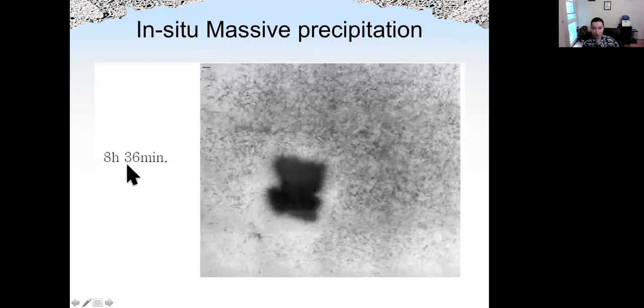This is 8 hours. We can see more hydration product precipitate on this cement grain, and also we have more hydration product generated in the water solution. When that happens, the cement is no longer fluid. It begins to become solid and gain strength.